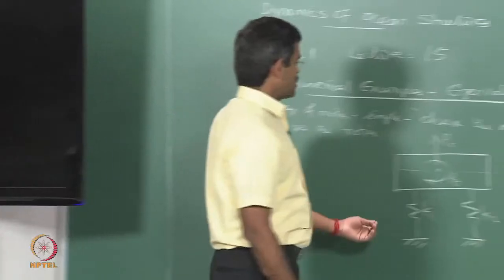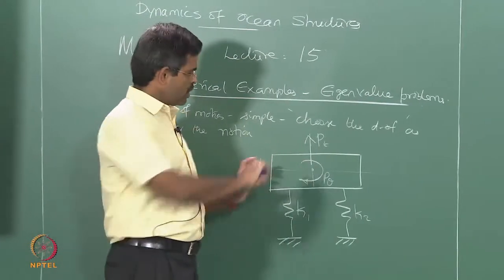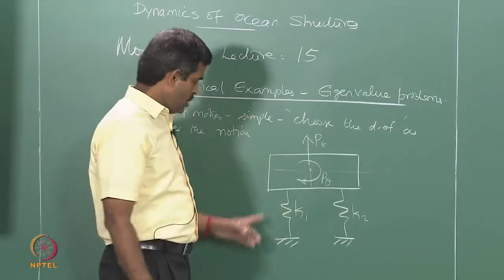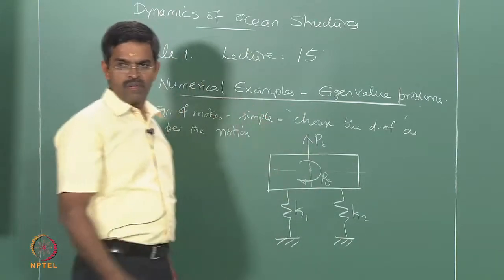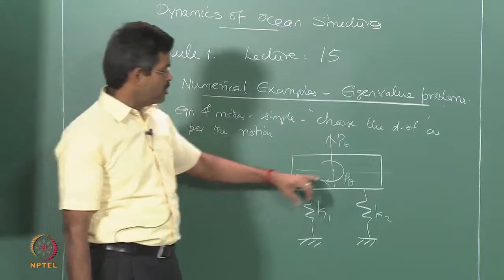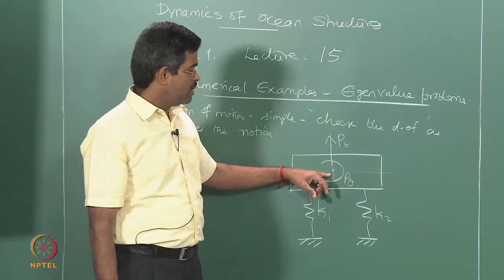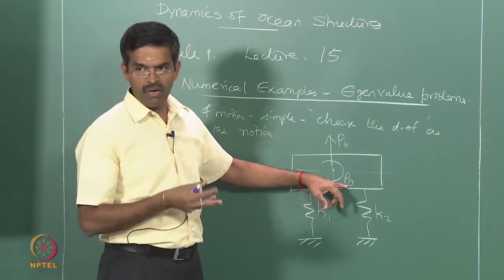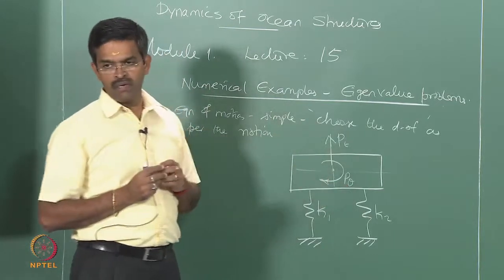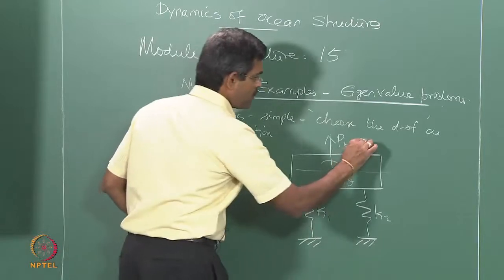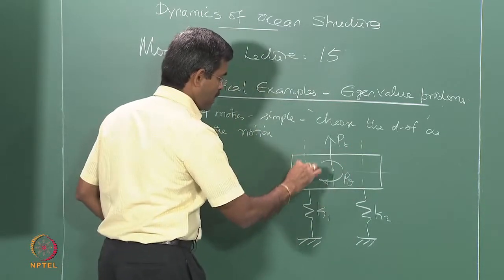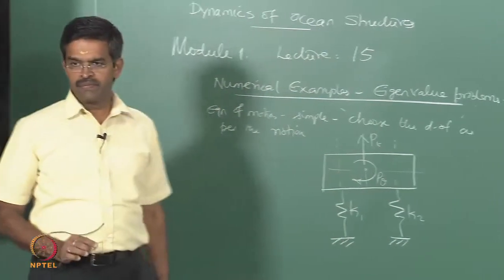So, the force in the vertical axis is applied at the Cg point and the rotational motion is also applied, because you know the springs have different stiffness. So, the pad will keep on oscillating, it will create a motion or a rotation about this point Cg obviously. Therefore, we take that as the force P, theta is the moment applied and this is the vertical force, whereas the degrees of freedom are marked at the points where stiffness is applied.